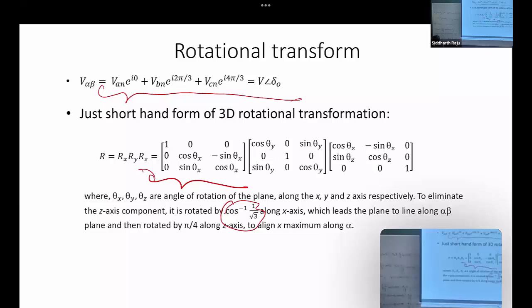Right, perfect. So we don't lose any information here, because going from the three-dimensional space, we appear as if there are three variables, but there are actually only two independent variables, and we are conserving all the information. So once we go to space vector, we can directly come back to our time domain values, which we'll take a look at later. Pretty straightforward, it's just projection in the space vector to the particular axis that we are interested in. But the information is preserved there, right?